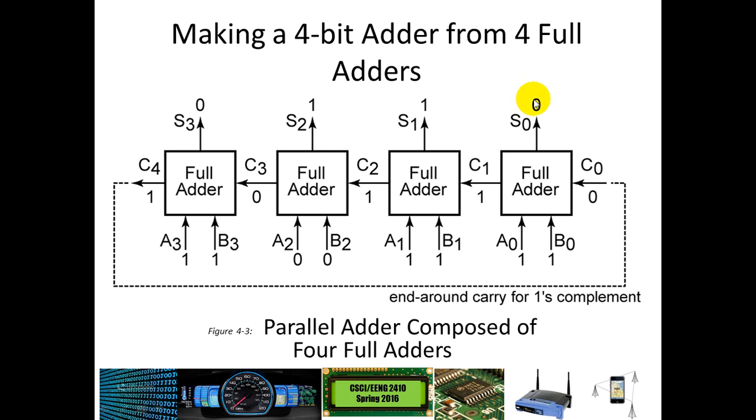In this case, we can only represent a 4-bit sum. We have 4-bit architecture here. So if this sum were supposed to be a 1, then that value would be too large. In this case, you can actually tie your carry out into your carry in if you wanted to form the 1's complement of that particular value. So that's one way we can do that.